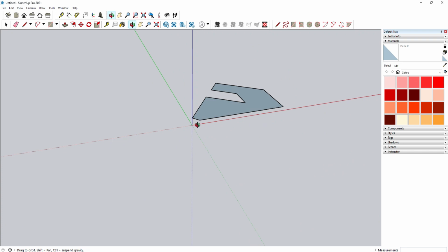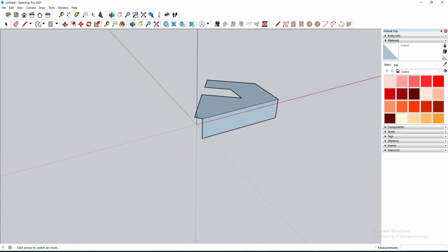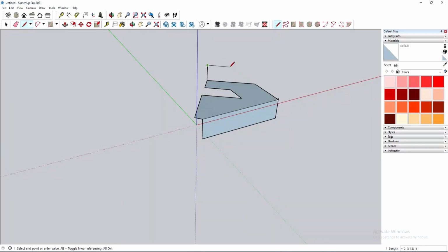To draw a rectangular vertical face, hover over the desired corner point and move down, in blue, and click when the double constraint appears. We will use a parallel constraint again. Draw a line up from the point shown. Move the cursor until the parallel inference appears. Press Shift to lock it and click the corner point.